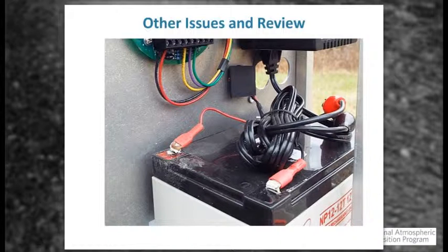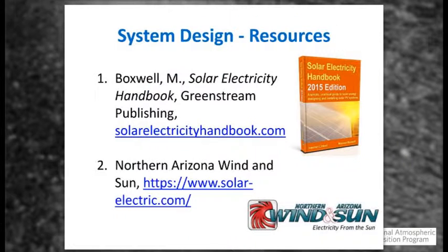This is a close-up of the inside of one of our electronic rain gauges, the ETI in particular. It has a separate onboard battery. You can see the terminal on the left, the red one, we're getting a bit of corrosion there. That leads to inefficiency. Sometimes they'll even get warm to the touch. So there's battery paste you can use to clean those up and to have a good corrosion-free connection.